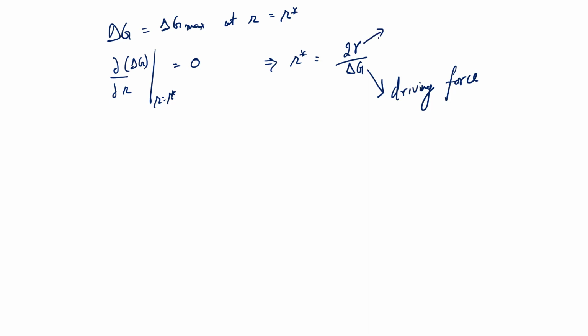On the other hand, the surface energy per unit area at the solid-liquid interface is a kind of obstacle to the nucleation. Okay, a kind of barrier. The larger the surface energy, the larger the critical radius.